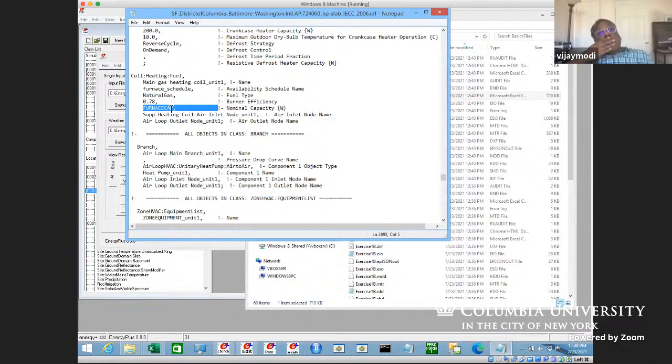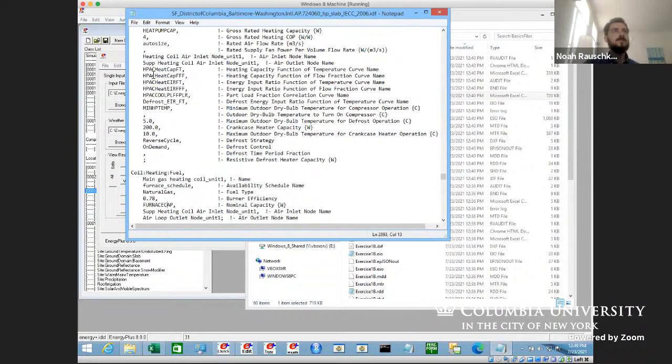And then I have an R script that loads this text file and individually creates new text files, replacing furnace cap with whatever capacity we want it to be, and then separately runs those simulations through a command line. So there's this kind of powerful thing if you like to do coding, where you can go in and replace things like minimum heat pump temp, and run lots and lots of different simulations by writing a piece of code to modify these IDFs.